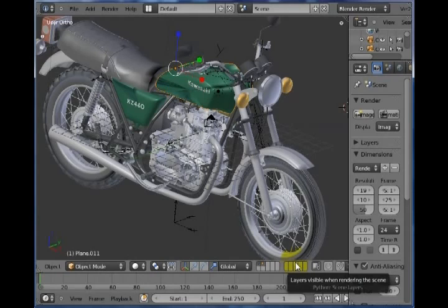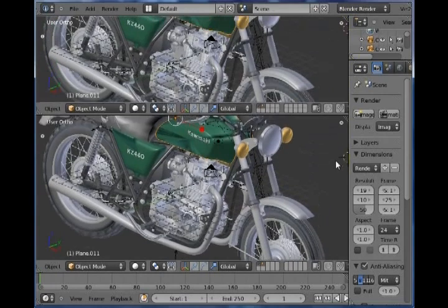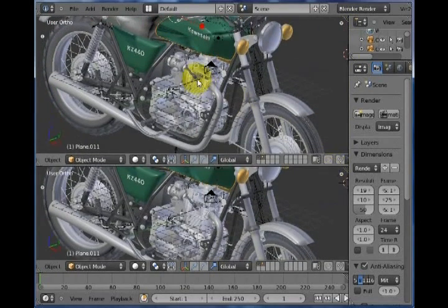So, we've kind of given you the basics on working with viewports. How do you split them up? How do you look at things in different views? And again, become comfortable with these viewing commands, how to maneuver around on the screen, how to pan, how to zoom, how to rotate, how to work within your principal views 7, 1, and 3. And we'll continue with some more practices in the next chapter.